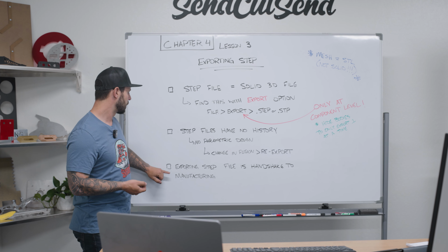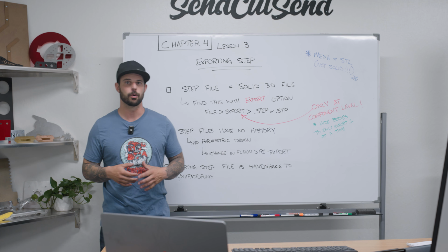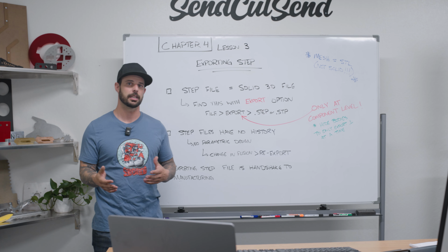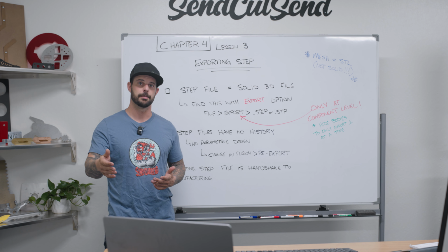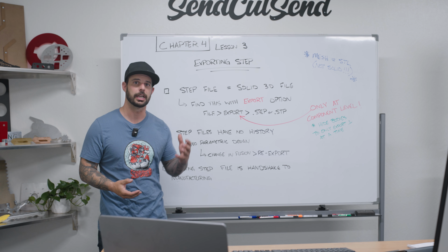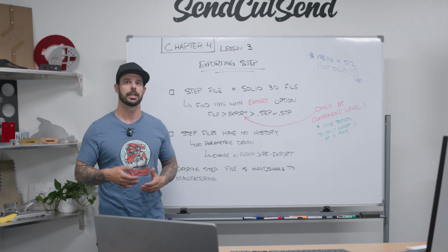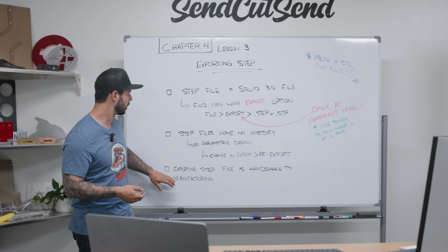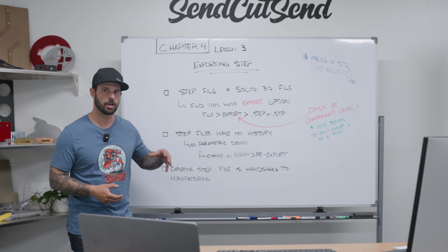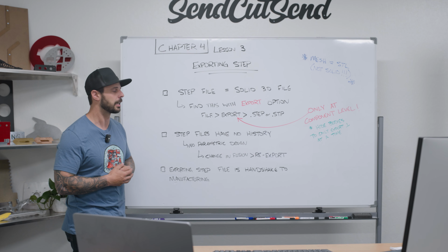Now, the last thing is that exporting that step file, or really any file, is the handshake to that manufacturer. They're not going to be able to make those changes because they don't have that history. And what you're saying is, this is an acceptable part and I need you to manufacture it, and that's that handshake situation. So know when you give that step file, they're hard to manipulate. It's kind of what we're getting at here.